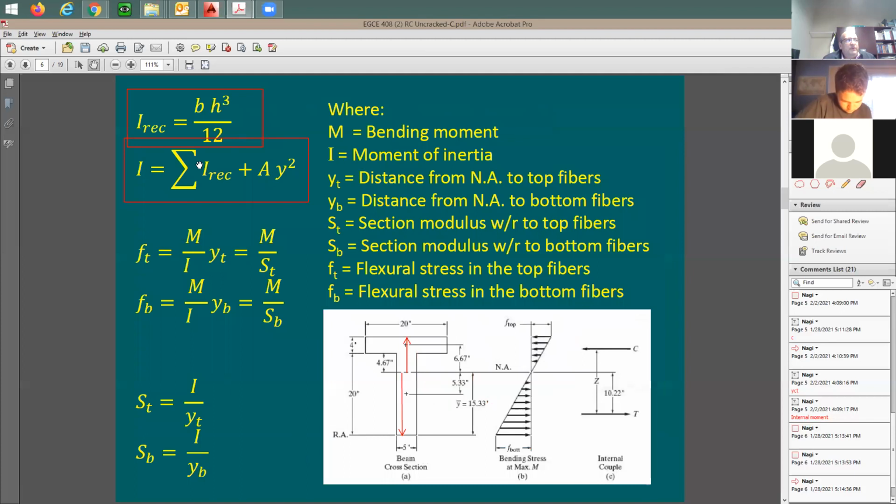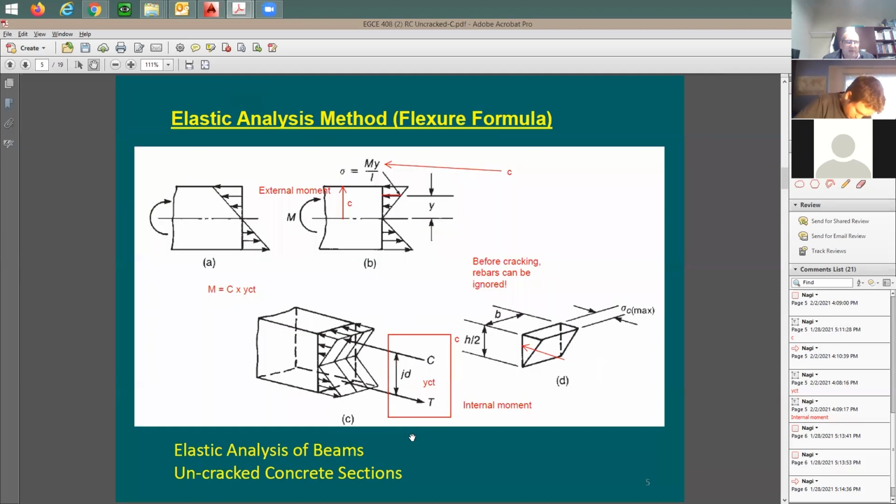So, okay, we went through this. We say here's the moment of inertia. I can do it for a T section. Now a T section is going to be a bit complicated. A rectangular section is simple, right? Because the stress top and bottom is going to be the same. And of course, the two forces are going to be the same. And the neutral axis is going to be right at the mid height. So you take this h over 2 and the bottom is also h over 2.